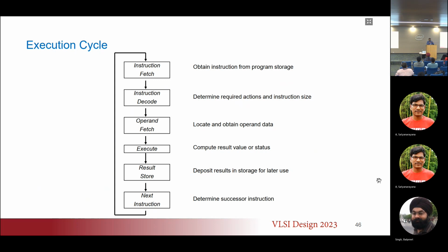And then you say add, every processing element is doing add. Then you say store, every processing element is doing store. How much instruction fetch have you shaved off because you're doing that? That just depends on the number of processing elements you have in parallel. By that factor, you reduce the number of instruction fetches, which is real savings in terms of memory fetches, memory stores, memory operations, and that gives you performance, and that gives you power.